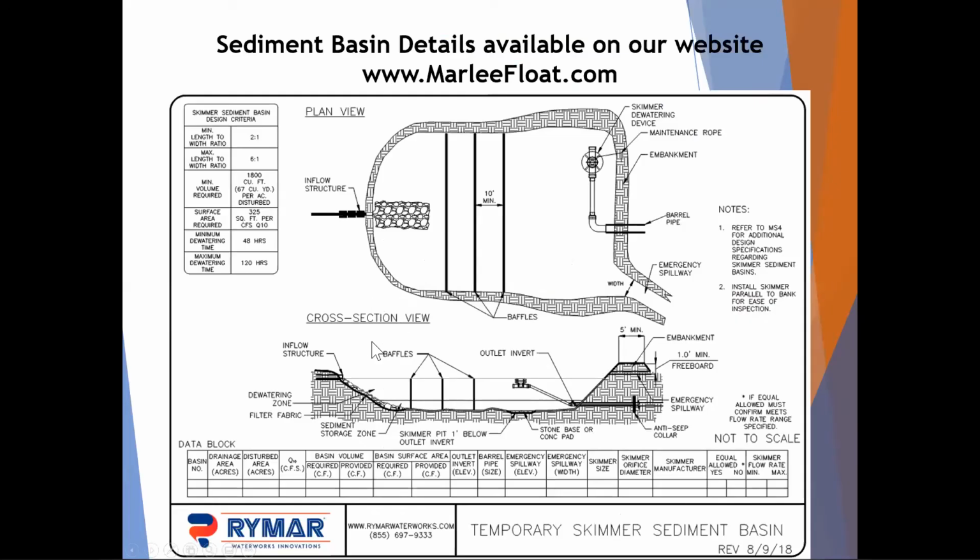We have also created sediment basin details. So our basin details are also available online for free. They're in CAD and PDF format. We have 4 versions. We have a basin detail for a temporary basin with just a pipe through the dam with no permanent pool, or we have a riser configuration, with no permanent pool. They both give you the basin criteria.